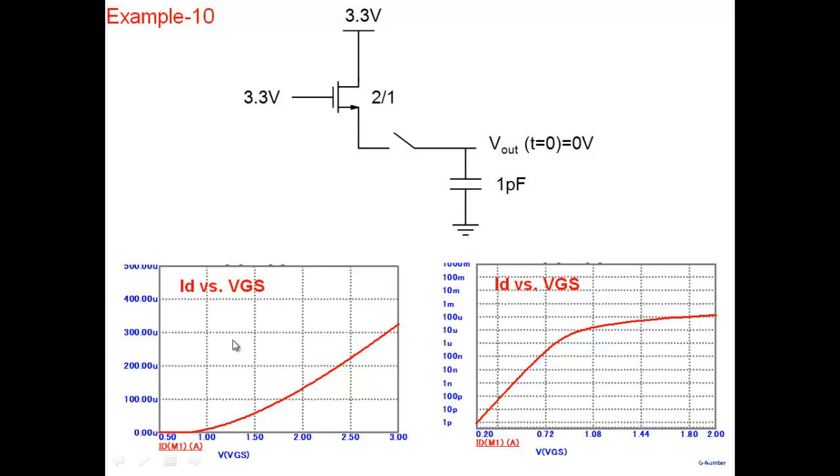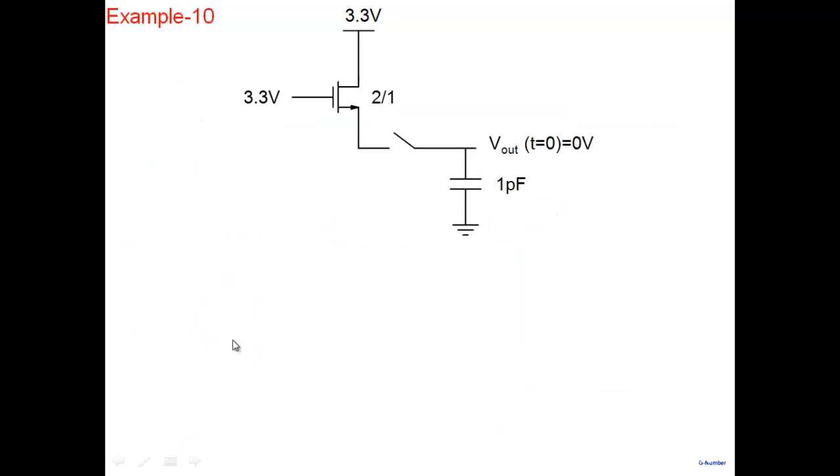Okay, so that's something that we neglected. You're right. As you are changing the source here, the body is connected to ground, so the source voltage is also rising. So VTH is also changing. That's the other complication that happens.